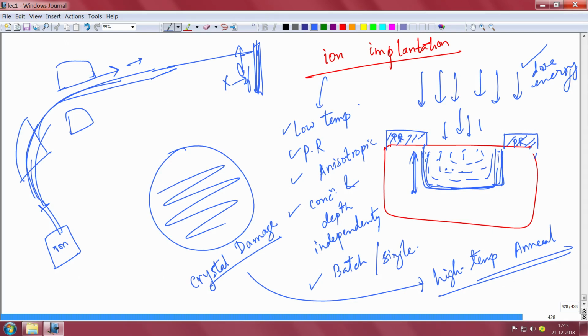And in ion implantation, of course, when you implant, it will not abruptly stop like that. As a function of depth, the doping profile will look something like this. So, there is a Gaussian distribution, there is a range to which you go, there is a straggle, the deviation, but anyways, with annealing you can approximate it as a uniform profile. Here you can get the depth and doping profile. It is very important, okay. So, that is an important aspect of ion implantation.